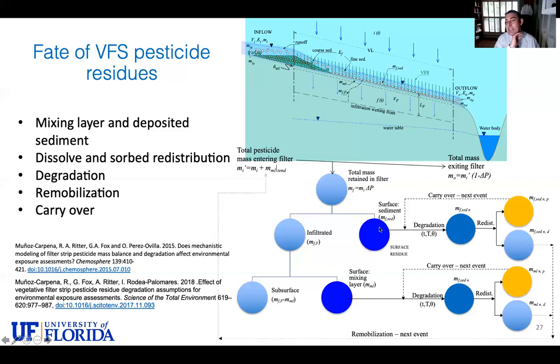And then of course the sediment amount stays on the surface. So every one of these fractions, the sediment on the surface and the pore water on the surface, dissolved and absorbed, goes through degradation on daily time steps. These are general degradation equations, exponential decay equations, modified by temperature and moisture content in the soil, because biological degradation is affected by these two factors. And then you have daily time steps until you get to the end mass before the next runoff event in the series. When the next runoff event comes, so many days after the previous one, the mass is redistributed again between the pore and the solid phase. Parts of that make it back to the surface to contribute potentially to the processes of, again, infiltration, settling, and so on. So we do a full cycle of where the mass is. And by doing that continuously, part of the mass gets resuspended and remobilized, so it adds to the expected mass out here, and part of that just sinks below the reach of the surface.